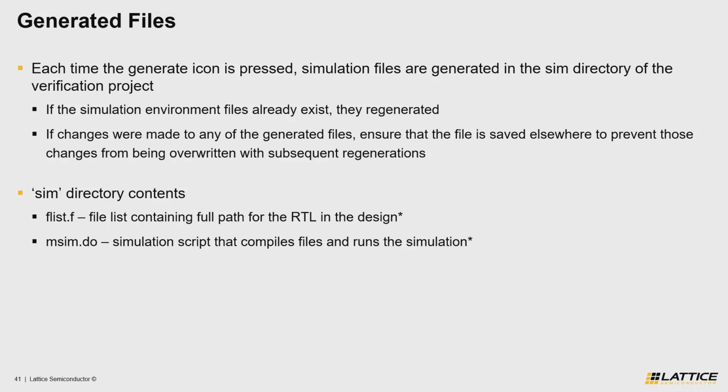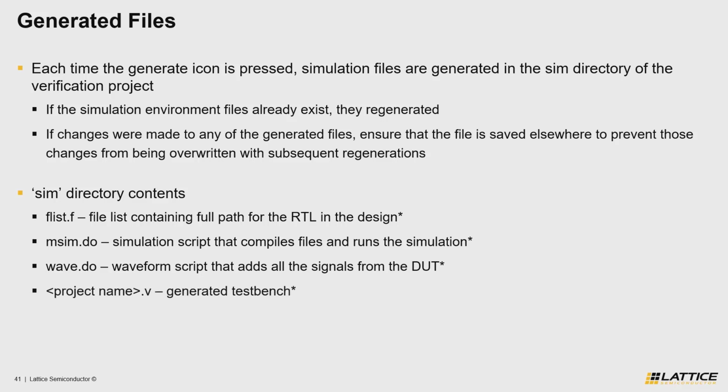With that said, the third file that you should know about is wave.do, which is another do script that adds all the signals from your DUT to your waveform display in ModelSim. This file is primarily used for organization, and can be modified to change the various signals or waveform configuration for the waveform display in your simulation environment. The fourth file that you should know about is the generated SystemVerilog test bench file, which is used to interface all of your verification IP with your DUT and provide stimulus. By default, this test bench only provides stimulus to initialize your design, and is another good candidate for modification in case you want to try different stimulus for your SoC project.